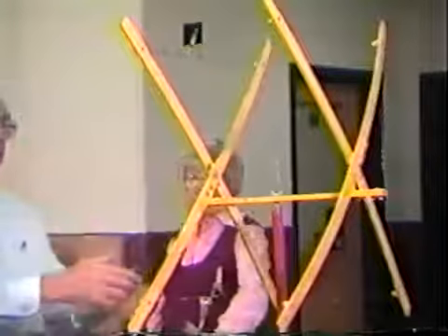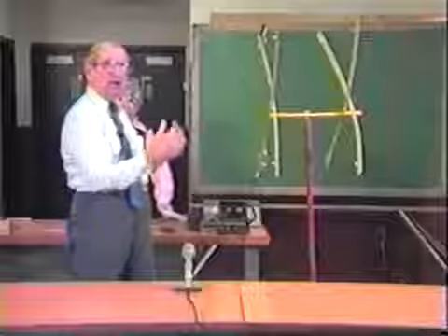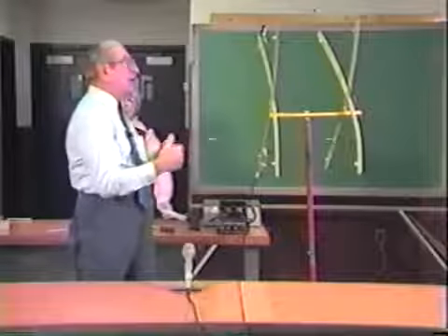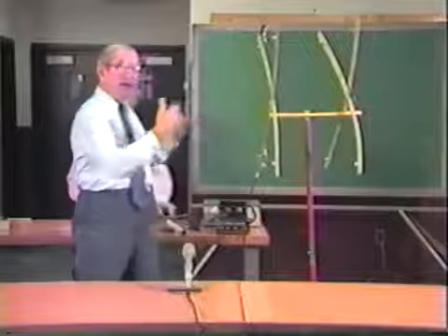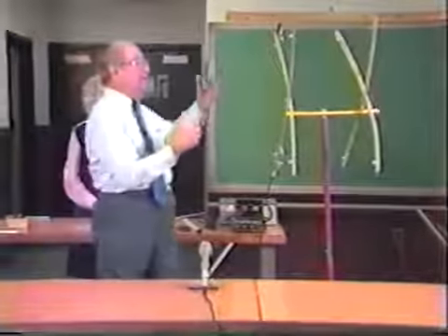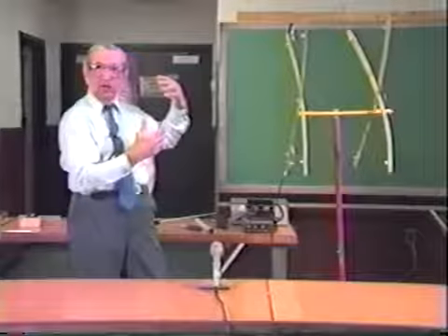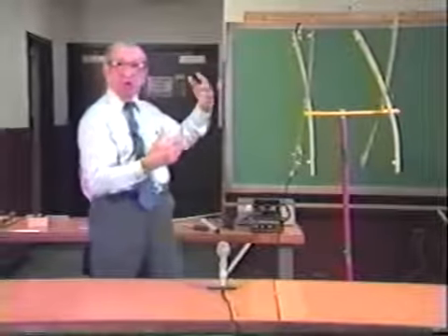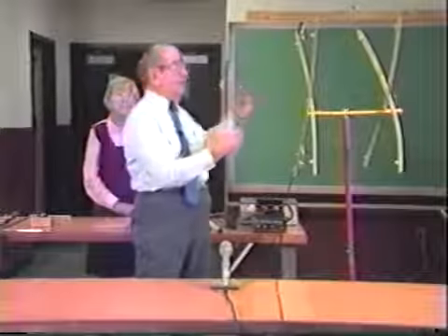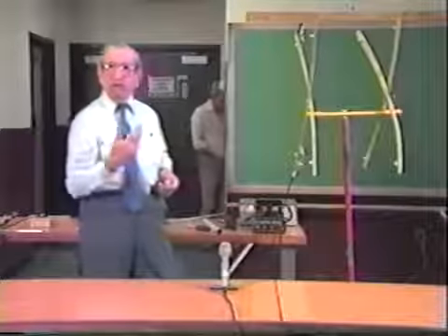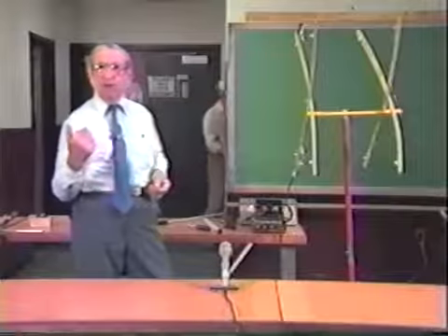Now, this is the portion that's doing the radiating of the electrical field and the radio waves. Since we have two radiating areas, they're both radiating and they're both tending to reinforce each other, so that this antenna has a little bit more gain than a two-element yagi. As a matter of fact, this antenna would be about the equivalent of a three-element yagi in actual effectiveness at the receiving end.